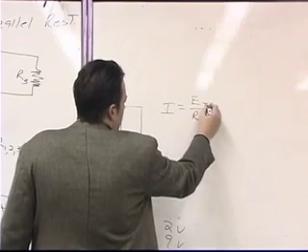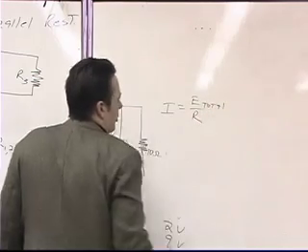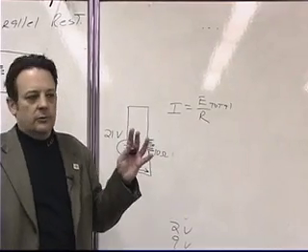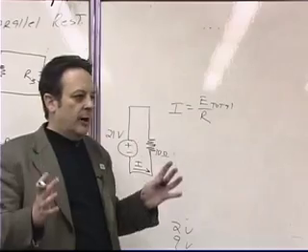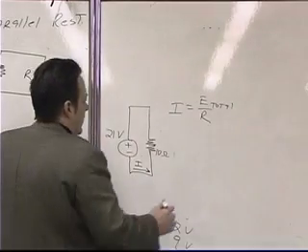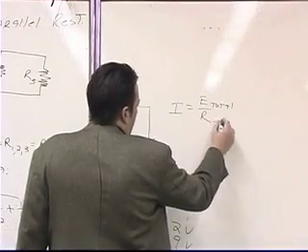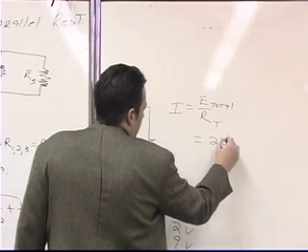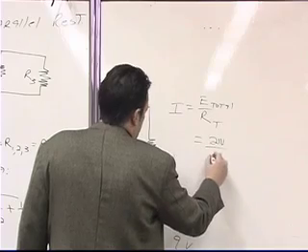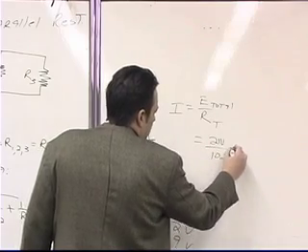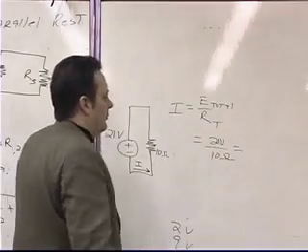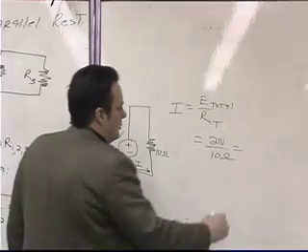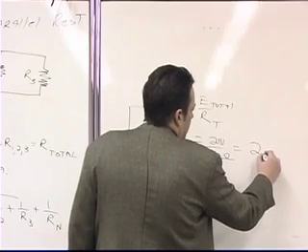So this is going to be truly the total voltage, because we had a whole bunch of different voltage sources. So we basically found the total voltage, and then we're dividing that by the total resistance, and obviously that's equal to 21 volts divided by 10 ohms. And what do you get when you take 21 volts and divide it by 10 ohms? You get 2.1 amps.